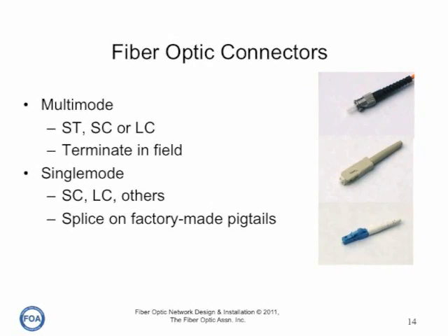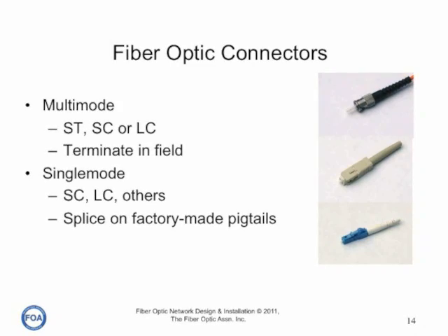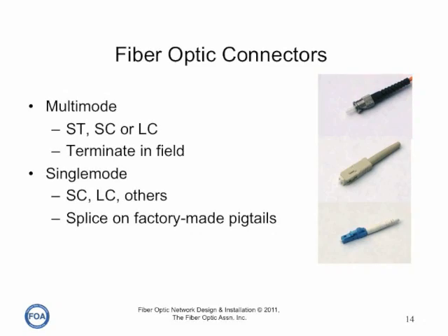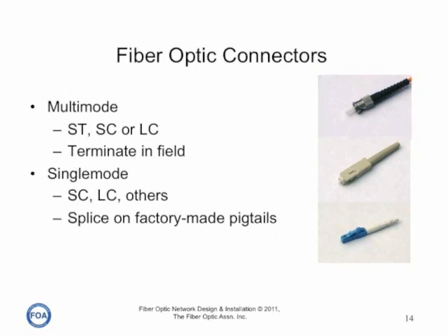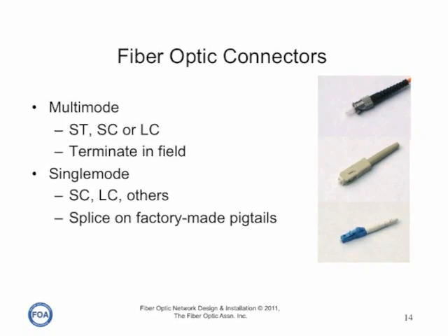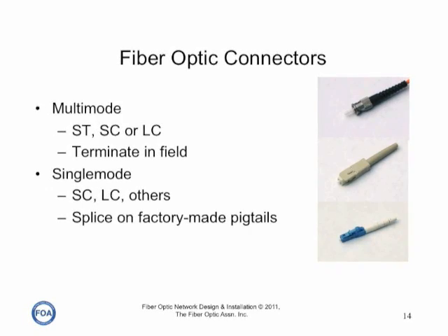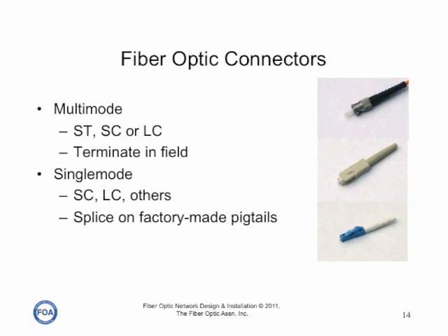Here are the 3 most popular fiber optic connectors: the ST at the top, the SC in the middle, and the LC at the bottom. In multi-mode, we generally terminate these connectors in the field, but in single mode, we'll splice on factory-made pigtails. Although in either case, you can use pre-polished spliced connectors.